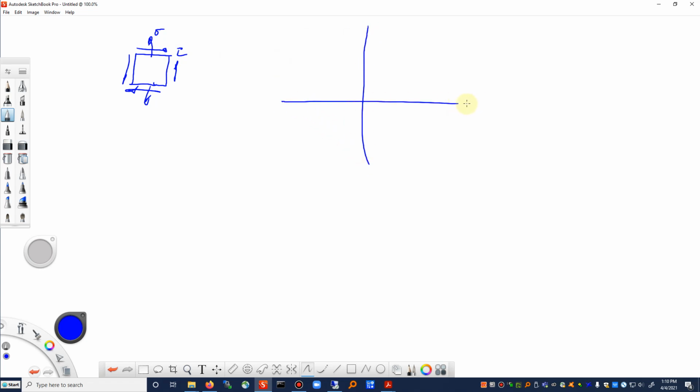I would usually have sigma on this axis, and then the square root of 3 times tau on this axis. A proportional loading path would go something like this, or in-phase proportional stressing. Now any kind of waveform that has the same function in time for sigma and tau will give you this type of path. Most frequently in testing machines we use sinusoidal waveforms.